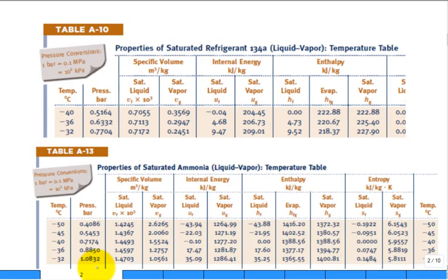So you have the temperature coming in for the saturation table for the refrigerants. This is for the 134A, and this is for the ammonia. Let's take a quick look. What is the lowest value of temperature in the 134A? -40 C. How cold is that? Very cold. But sometimes a refrigeration application wants to get something to -10 degrees, -20 degrees C, so they put the temperature pretty low in the tables. What else do you observe?